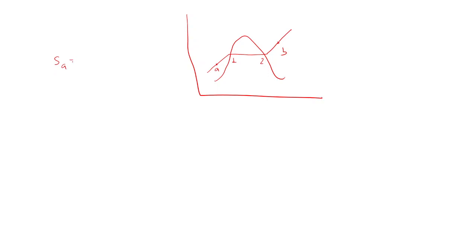So entropy at A is what? Anyone? Please repeat once. How will you calculate the enthalpy here at A, HA, if you have to find it? Sir, it will be H1 minus Cp, T1 minus TA. Correct for all?